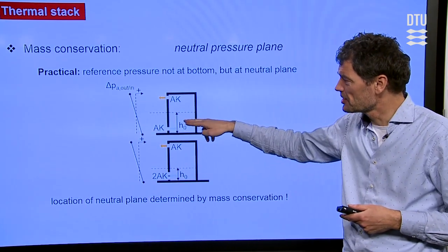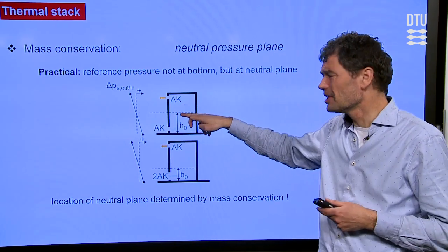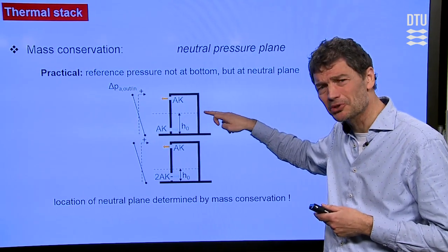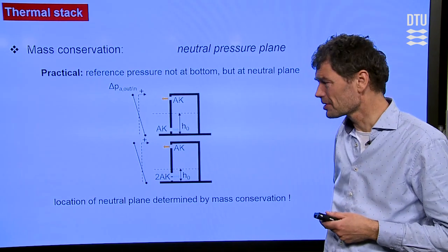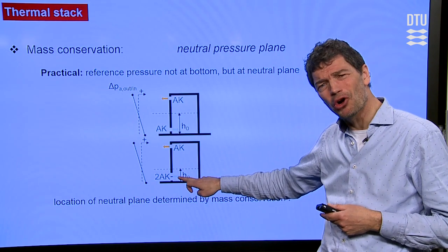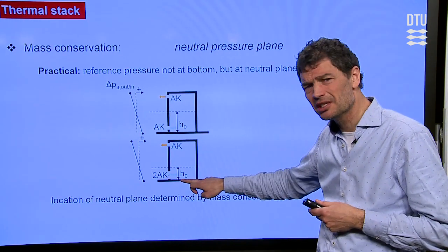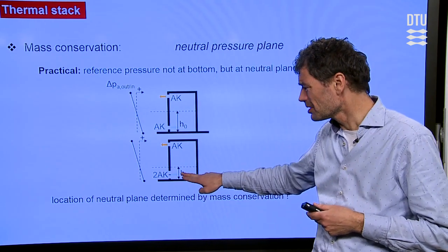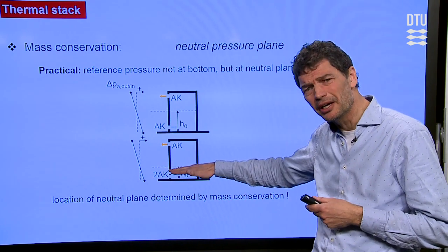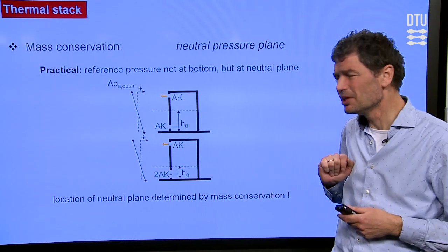That means that the air pressure, where it's the same between inside and outside, is in the middle of the height of the building. So we have a neutral plane, the same air pressure between inside and outside, in the middle of the building. If we have a similar building, but with a twice as big opening in the bottom of the wall, then it's easier to have air pressure contact in the lower parts of the building. And that means for my other building, the neutral height will be below the middle of the building, so it will be lower than what we saw from the other building.